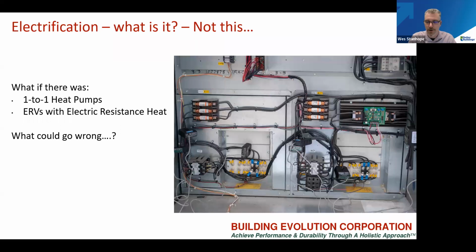The building's electrified. Well, in this case, the building is in the Northeast, with a cold climate in the winter. If you have electric resistance for heating after the ERV, and you are controlling that ERV by thermostats in the corridors, so you're using that ERV for space conditioning, then if you set that thermostat for, say, a 75-degree space temperature, that electric resistance is coming on a lot.